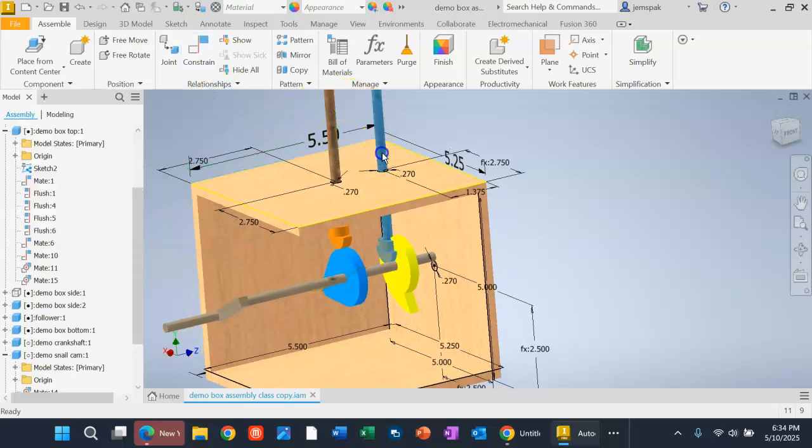And then I'm going to be dragging this up a little bit so I can see what I'm doing. So I drag that up. Now I want to get this so that when I turn this, right, see how it goes through and kind of like as though it's invisible? We don't want that. So I want to do two things. I want to line it up and I want to have it actually be there, like physically the way this cam is. So I'm going to do a constraint again.